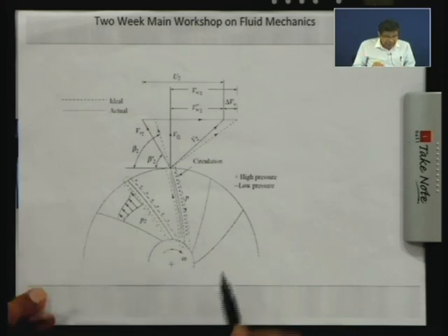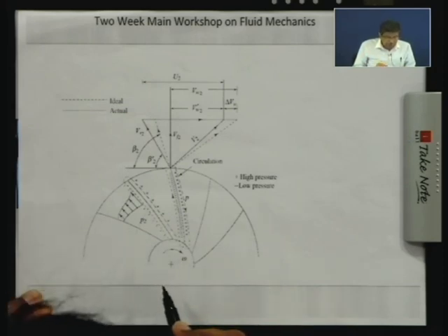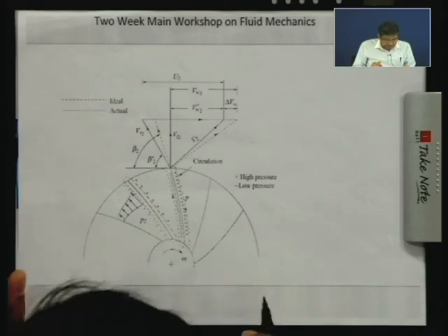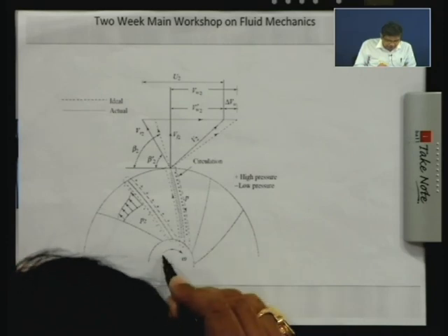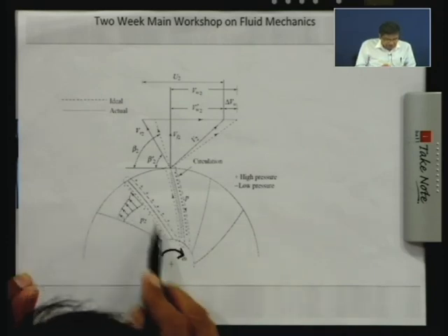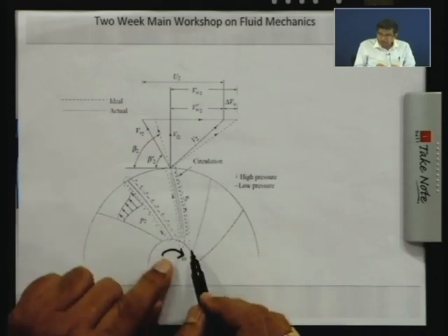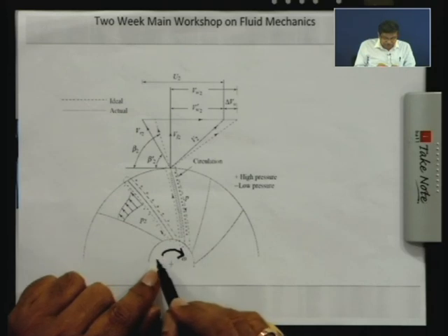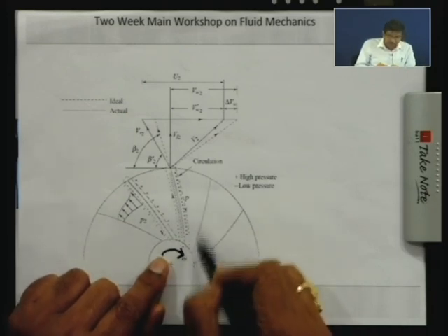Now, earlier we have discussed the velocity triangle. Here, of course, in the figure which I have taken, earlier the velocity was in the opposite direction; here the velocity was given in this direction, it does not matter. Accordingly, the impeller blade is like this, because impeller blades are always backward curved facing. You see, this is the direction of rotation, and it is curved in the opposite direction like this.